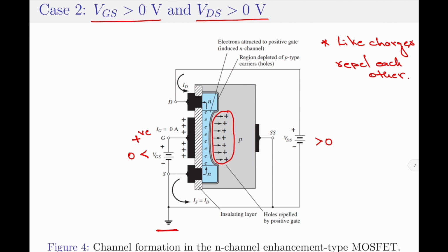However, at the same time the positive charge carriers are moving away from the silicon dioxide layer, the electrons in the p-type substrate material, which form the minority charge carriers in the substrate, will be attracted to the positive gate voltage, and now they move in the opposite direction to that of the positive charge carriers. Since the positive charge carriers are moving away from the gate material, the electrons will move towards the gate material, that is towards the silicon dioxide layer.